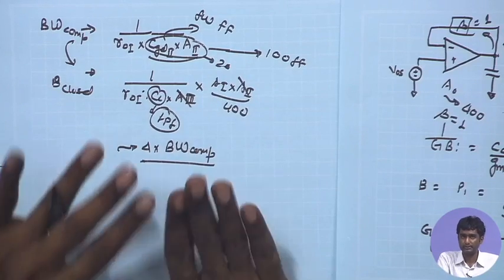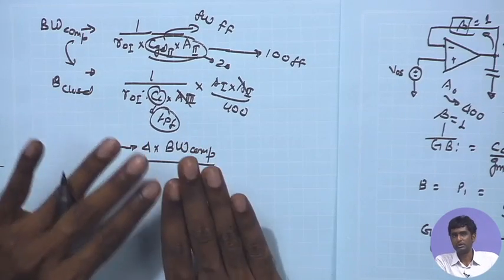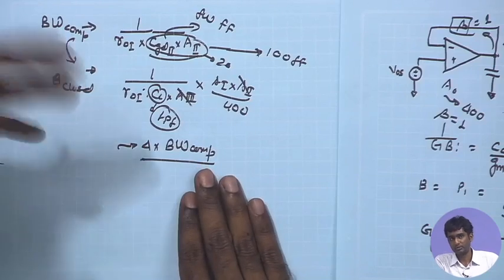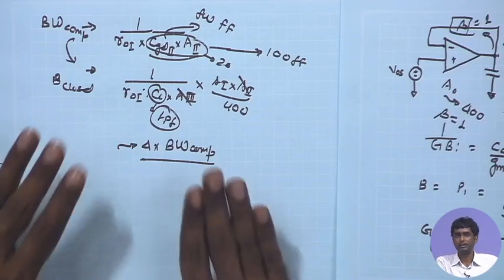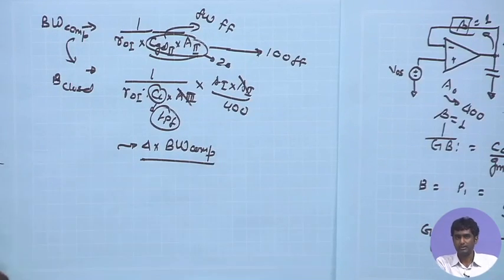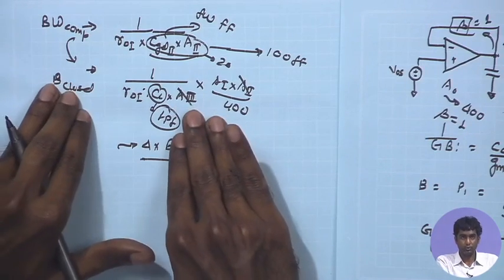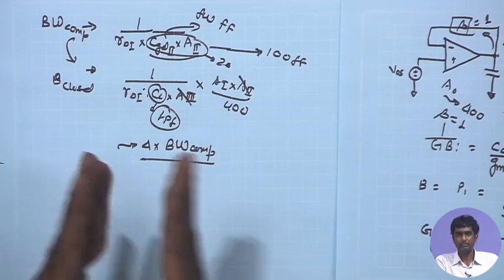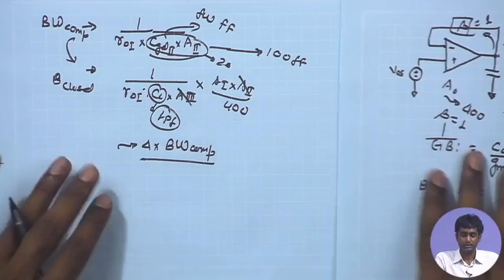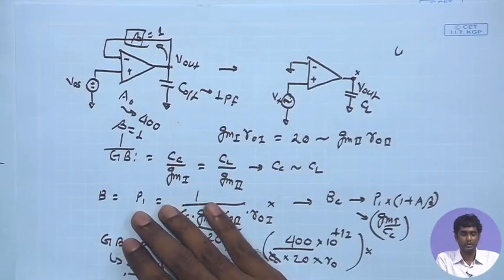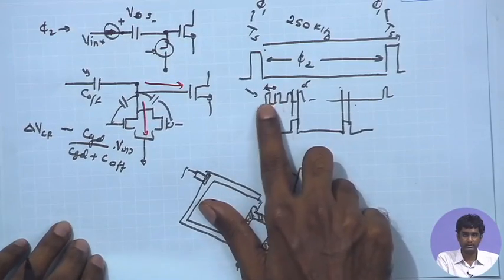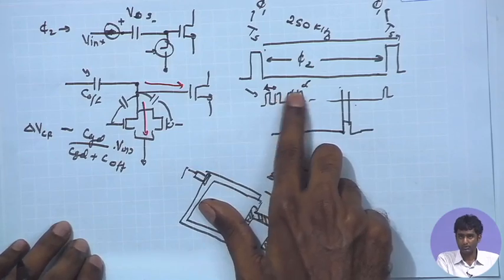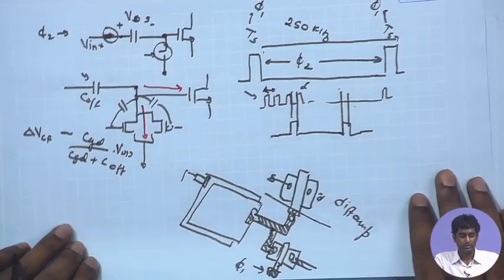We conclude that yes, this is good enough and fast enough compared to the open loop operation, and it can do the offset sampling within a single clock pulse of our ADC. And then we discussed the case where it goes down and becomes smaller than this, what the implication is, and how to handle that by modifying the control in the offset cancellation loop, using more of these clock pulses for the offset cancellation rather than just one.